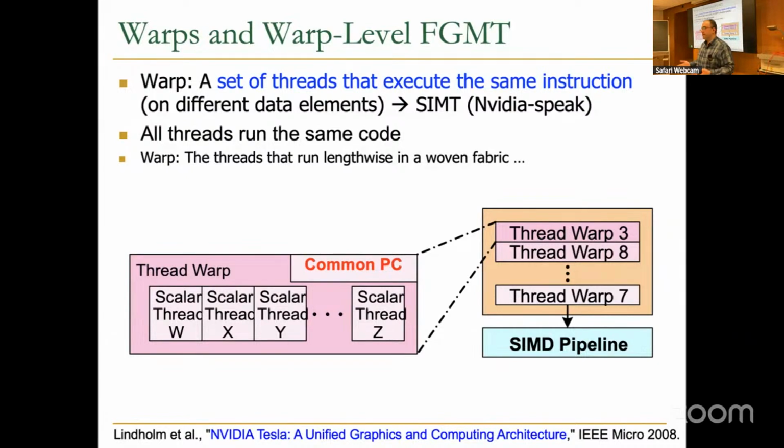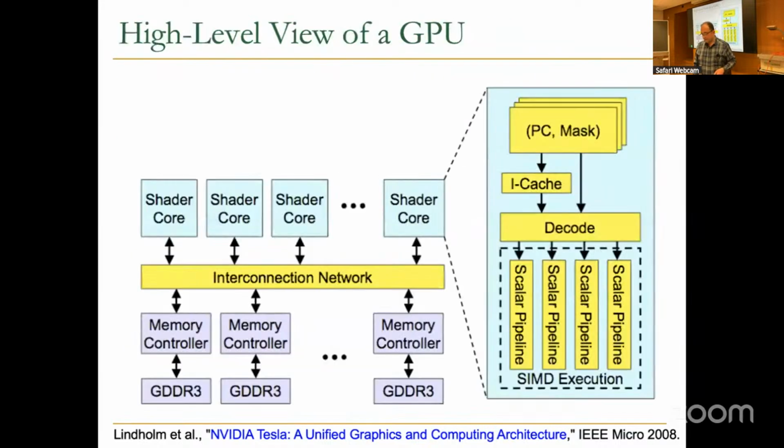So the backend of your execution in a GPU is actually scalar in a vector. You have a scalar functional unit, which can also be pipelined. That's why we have it like a vector processor. But then we have several of them, which is similar to an array processor. That's how we combine these two together. It's a high-level view of a GPU.